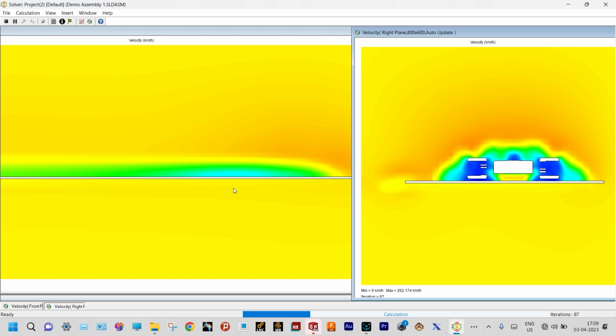In this analysis, our main aim is to reduce the drag coefficient or drag force. Drag force is actually the force in the x direction that is to be reduced. As a global goal, we have already determined force in the x direction, that will be the drag force. Excluding that one, we could have determined the drag coefficient, and that can be obtained from the equation goal. But at this moment, we are not providing it. We'll show how to find this drag coefficient in a different analysis.